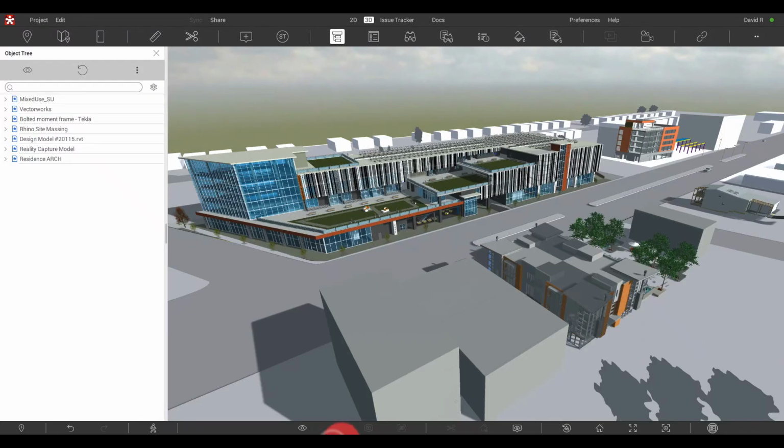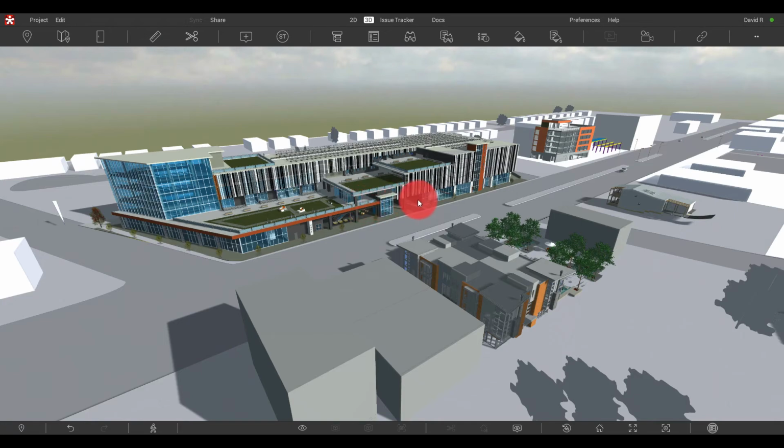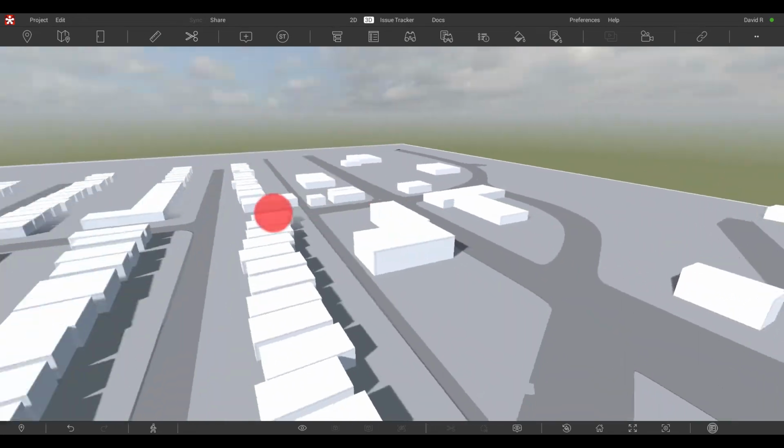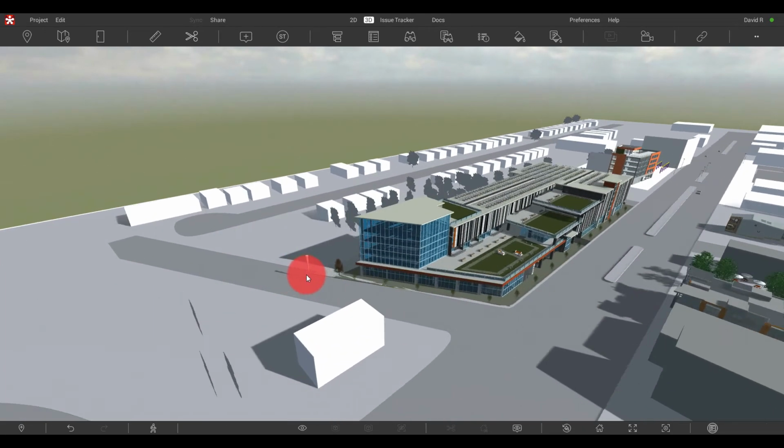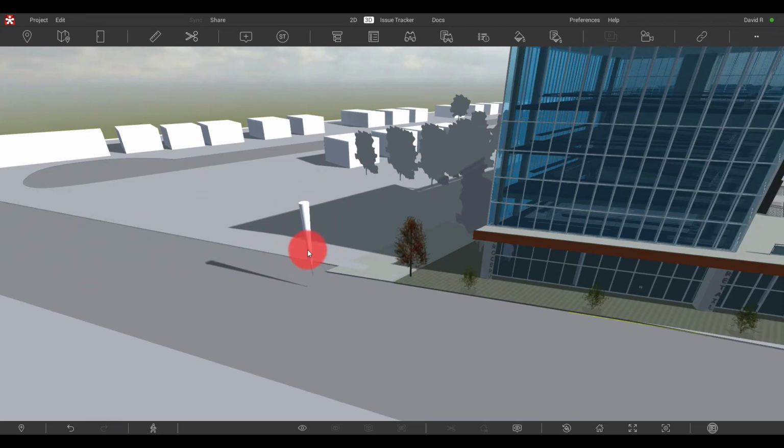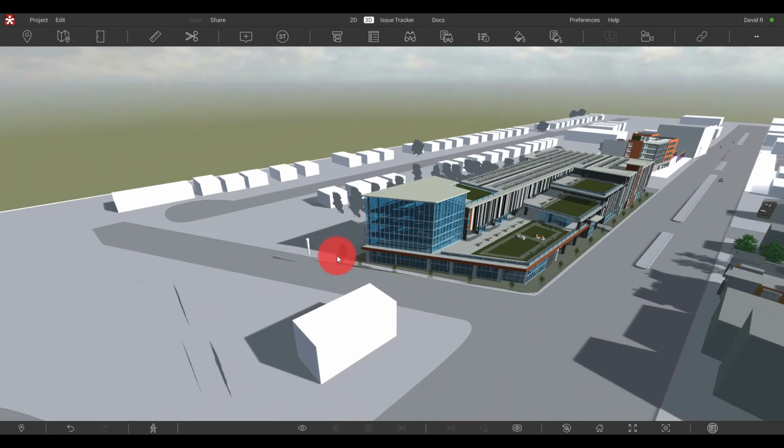So I'll cancel out of that, go into Revizto, and talk a little bit about how the model came in. Again, looks pretty good with the rendered view setting. Again, something to keep in mind, the small pin icon and how I position this model. Where this is really helpful, for example, if I needed to move the site model in place in relation to one of the other buildings in the project, maybe the Revit model, now I have a really clear way of referencing where this model is positioned at the origin point. This pin representing the 0,0,0 value I brought over from Rhino.